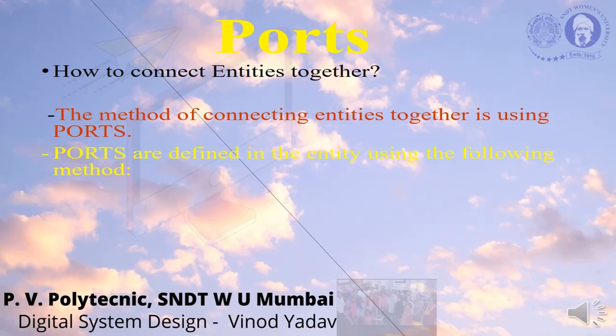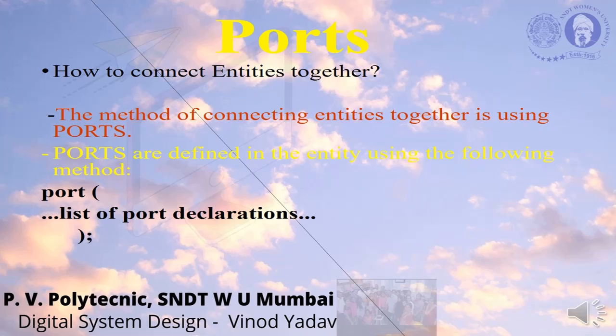Ports are defined in the entity using the following method: open bracket, then the list of port declarations. Whatever ports you are defining, say A, B, sum, carry, these are the things we will be defining here, and then we close it like this: close bracket and semicolon.